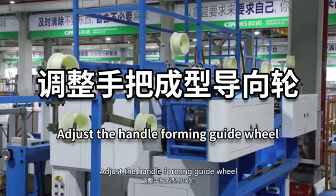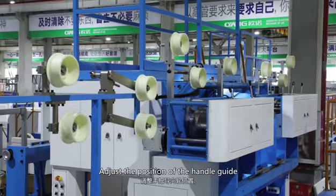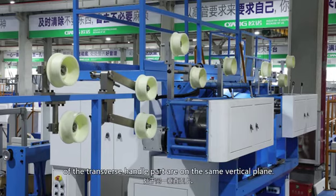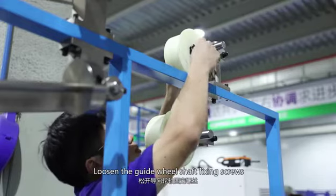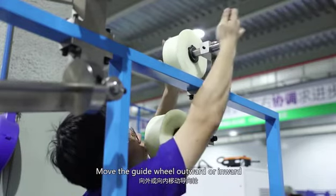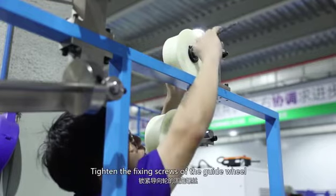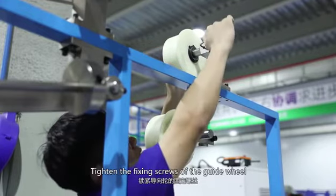Adjust the handle forming guide wheel. Adjust the position of the handle guide wheel so that the convex table surfaces of all the guide wheels and the convex table surfaces of the positioning plate of transverse handle part are on the same vertical plane. Loosen the guide wheel shaft fixing screws. Move the guide wheel outward or inward. Tighten the fixing screws of the guide wheel.